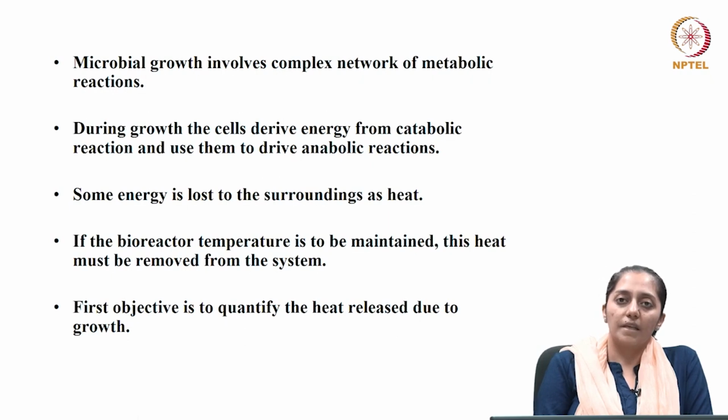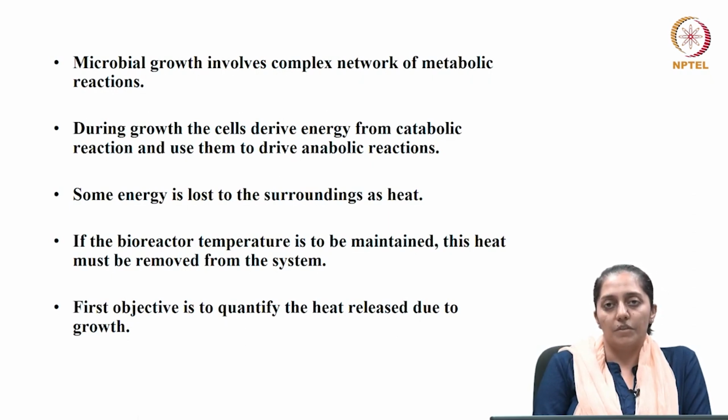Let us characterize some of these heat transfer operations which are known to happen in any generalized fermentation process. So, microbial growth involves a complex network of metabolic reactions. Now, during the growth of the cells, they derive energy from the catabolic reactions and use it to drive the anabolic reactions. Some of this energy during this process is lost to the surroundings as heat. Now, if the bioreactor temperature is to be maintained at an optimum value, then this heat must be removed from the system. So, the objective is first to quantify the heat released due to the growth of the biomass, which we may term the metabolic heat.